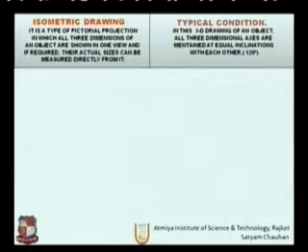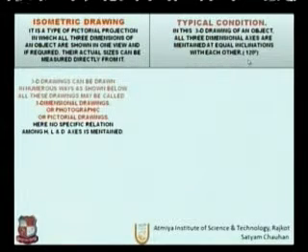In 3D drawing of an object, all 3 axes are mentioned with equal inclination to each other. In isometric it will be a 120-degree angle formed by 2 lines, and whatever drawing we produce will be produced within the 120 degree angle. It can be drawn in numerous ways as shown below.